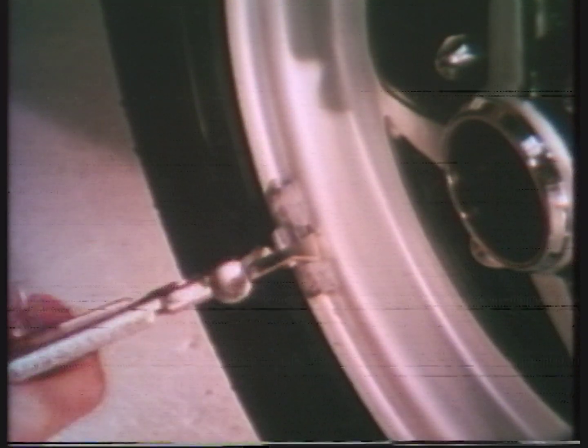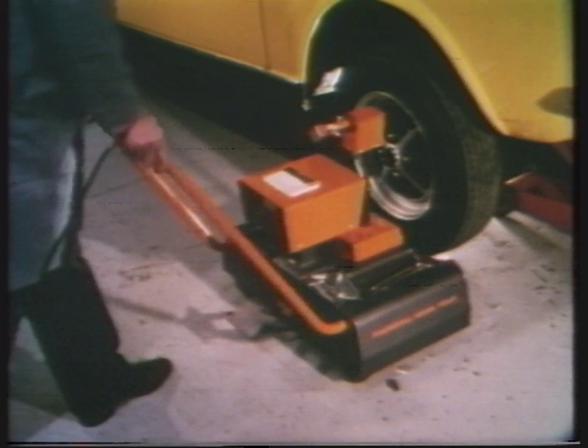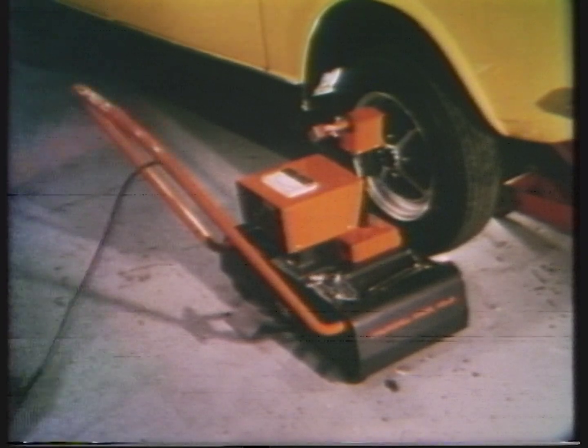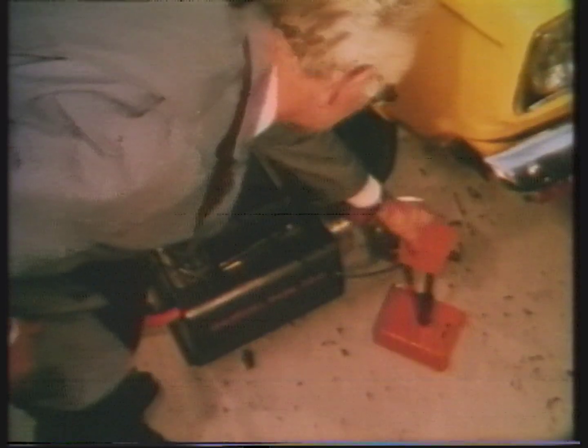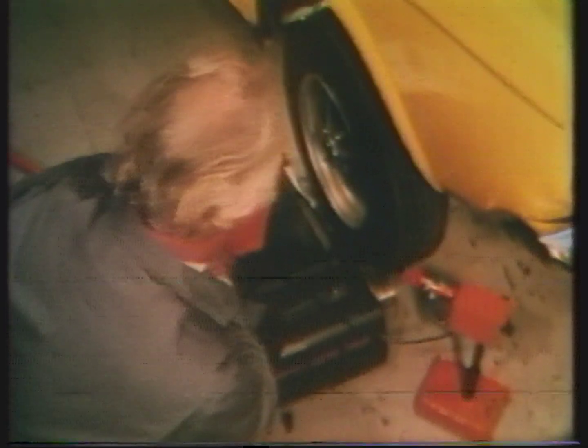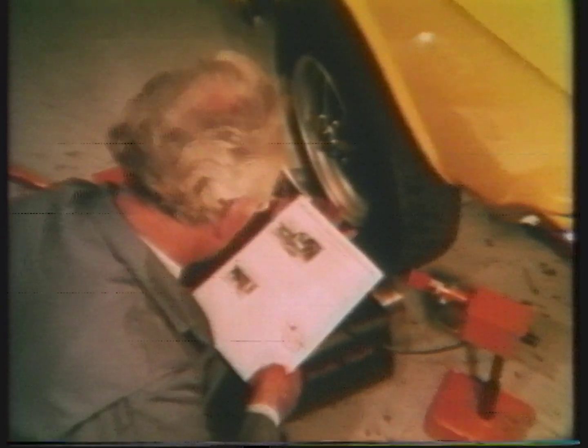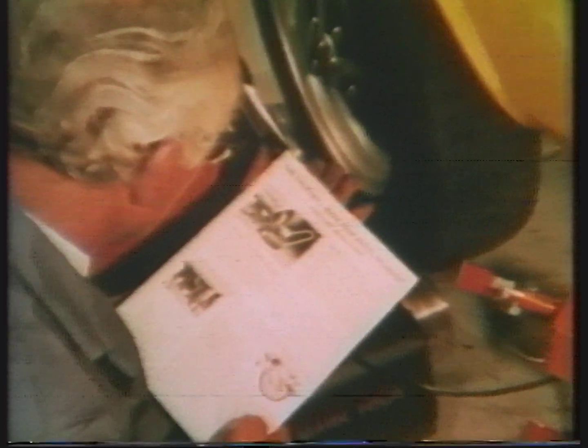Remove existing weights. And don't forget mud and stones in the tread and loose material inside the tire. Even balance weights have been found floating loose in there. Incidentally, an on-the-car balancer is to be preferred. And do read the instructions issued by the manufacturer of your particular machine. Those of you who are unfamiliar with the procedure should follow it step by step, whilst the experienced might easily find they're overlooking some finer points.